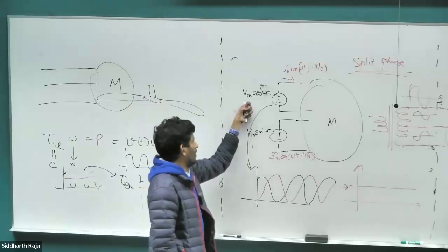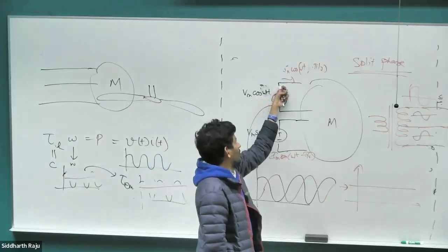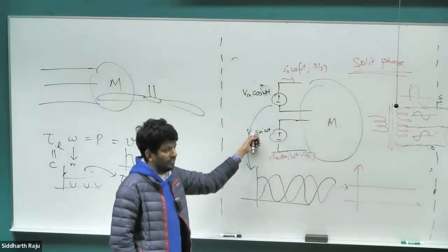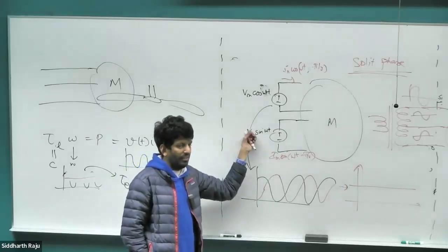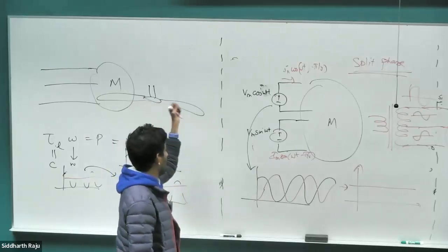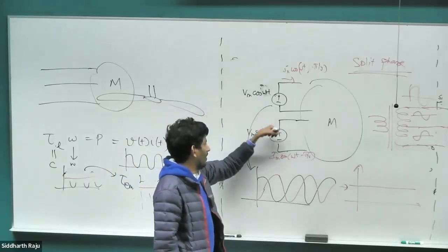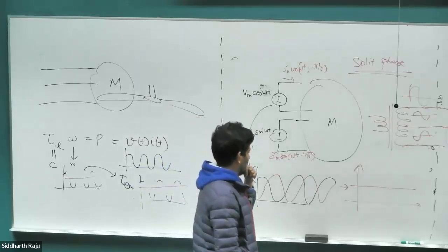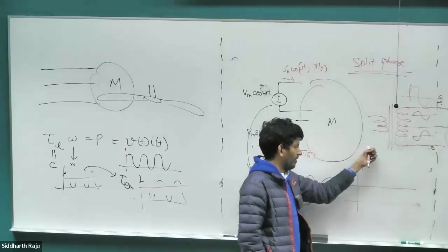So if I have this voltage and I put a capacitor in series with it, the voltage after the capacitor would be 90-degree phase shifted, effectively making it appear as if it's another two-phase voltage source, right? Just for a short instant of time. And then once the motor starts rotating, the other winding will be disconnected and it'll just run off the single-phase system. Okay. So typically you won't see a two-phase system other than that.